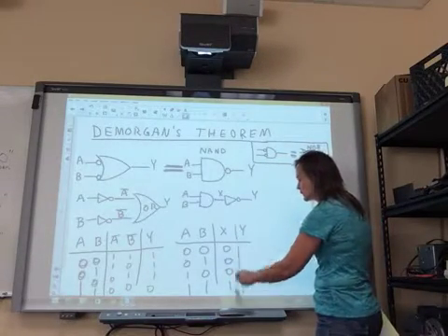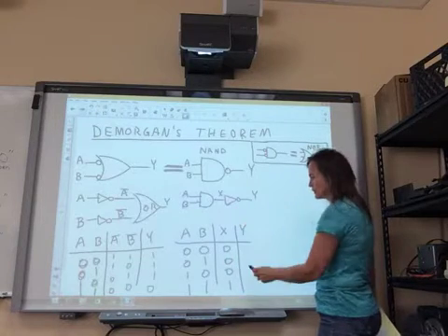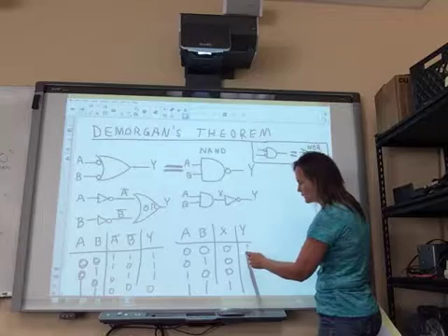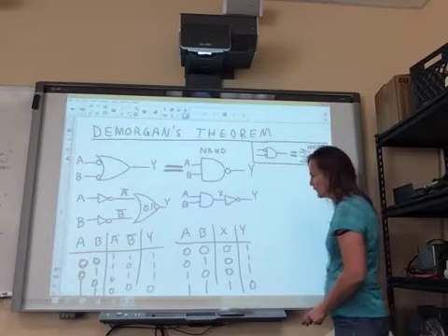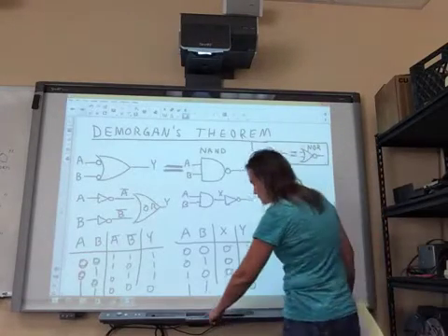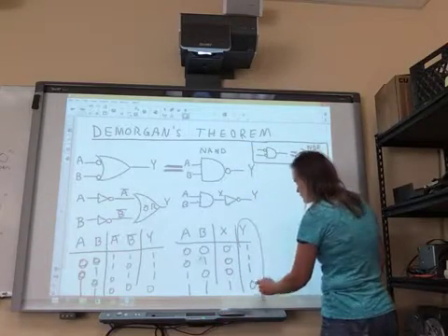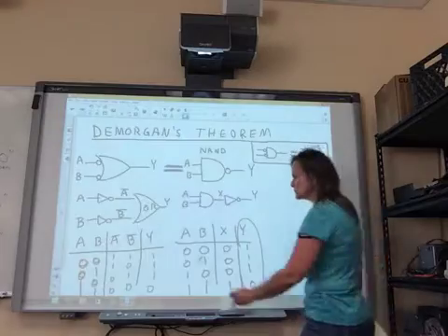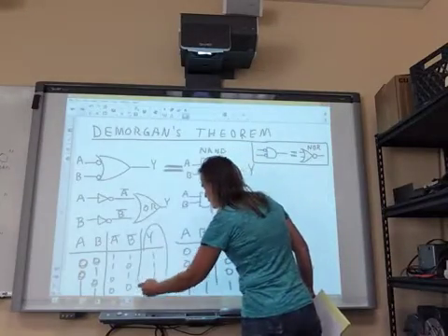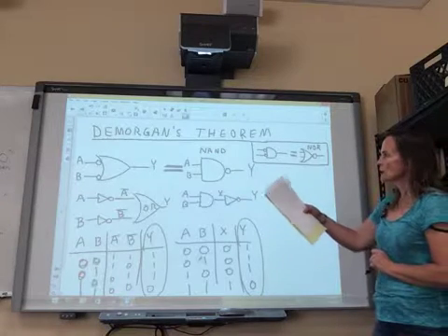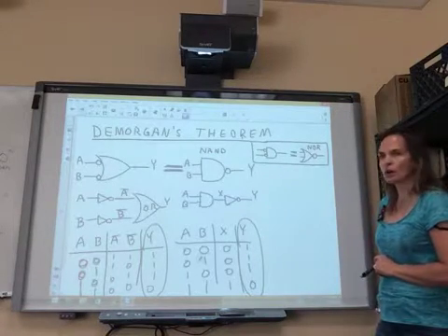And we're simply going to send this result now through the inverter, so anytime I get a low here, I get a high here, so we get high, high, high, low. Now the thing I want you to notice here is we've just proven DeMorgan's theorem, where every possible result is the same for these. So indeed, these two gates are equivalent.